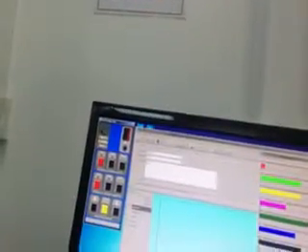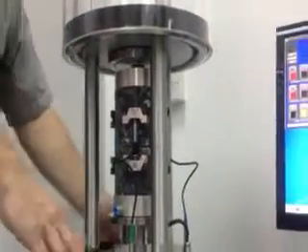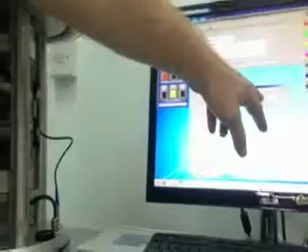20.8. Okay, to lower the cell, you can press the lower button. Now the cell will not automatically fall down. For protection, to stop if someone's hands are inside here, what you must do is press the interlock buttons. So you need to use two hands to lower it. That stops you from having a hand in here. Yeah, so you have to hold these buttons down, both buttons together. It's not coming down very fast or with a lot of weight, but you can still be hurt.